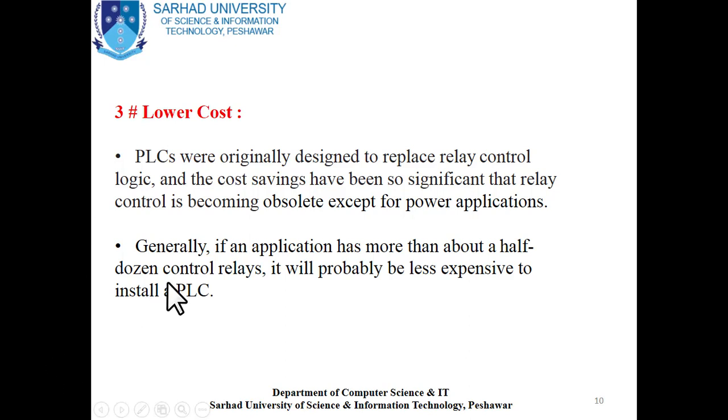The second point is that generally, if an application has more than about a half dozen control relays, it will probably be less expensive to install a PLC.